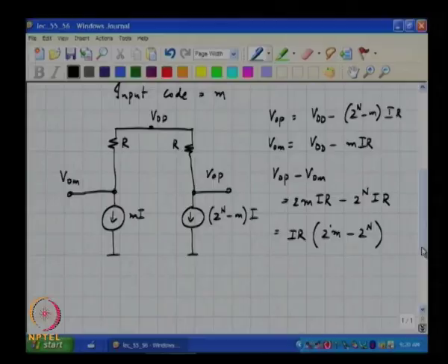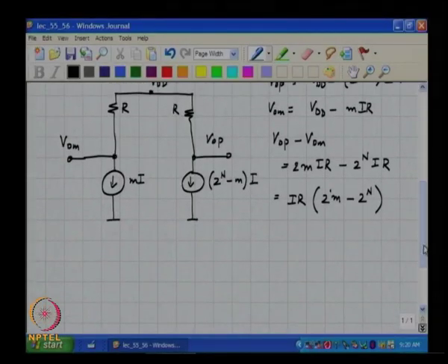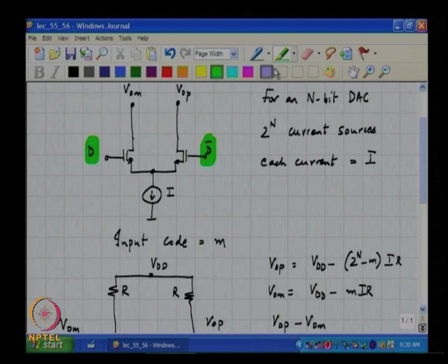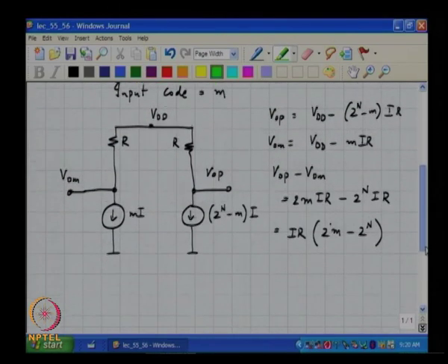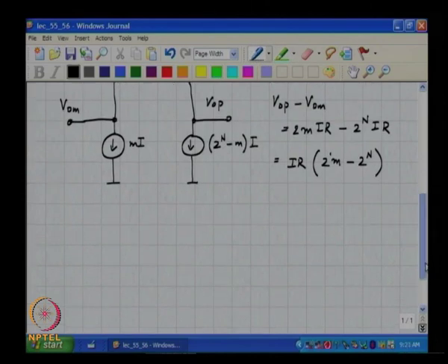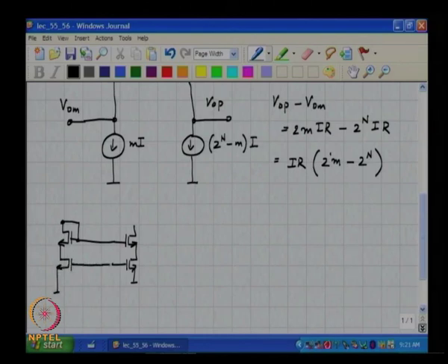Okay. Now, unfortunately, each of these current sources will have a finite output impedance, and therefore, what happens is that this current source is not ideal. Please recall that as we were discussing the last time around, these current sources are actually implemented using MOS transistors, and an example of a good current source where the output impedance has been enhanced is to use some kind of cascode.